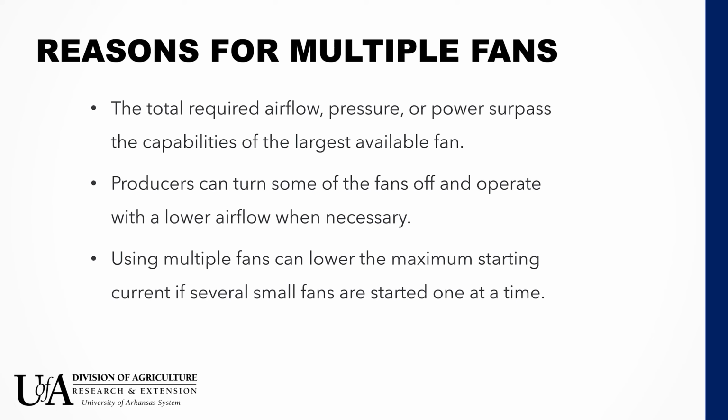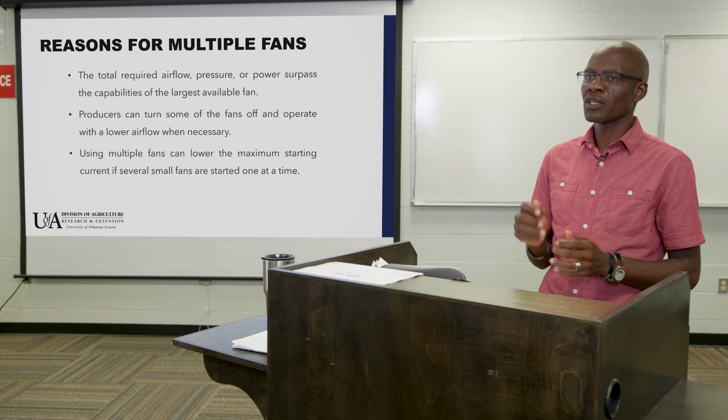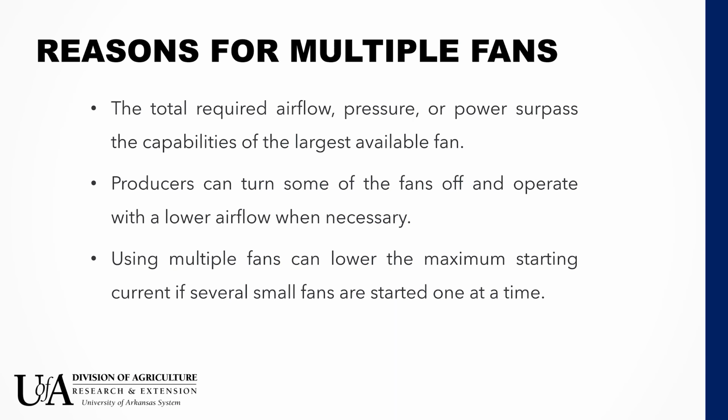There are also cases where we are restricted by the current that we want to draw from the line. When we have bigger fans, we need to draw higher currents to start with. But if you have multiple fans, it's possible to start one fan at a time, and by so doing, we end up having lower starting currents.